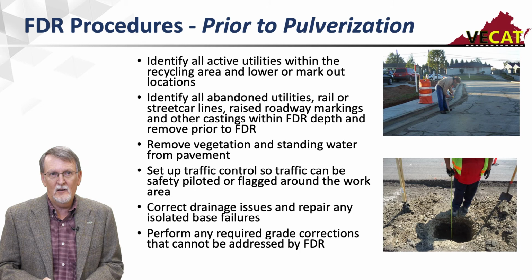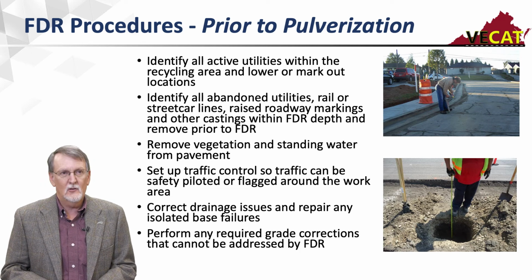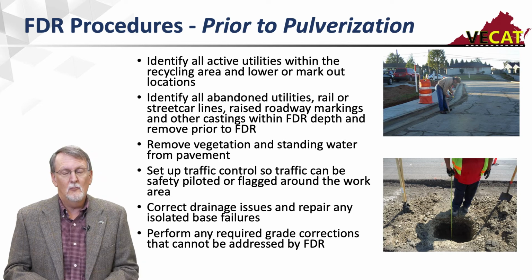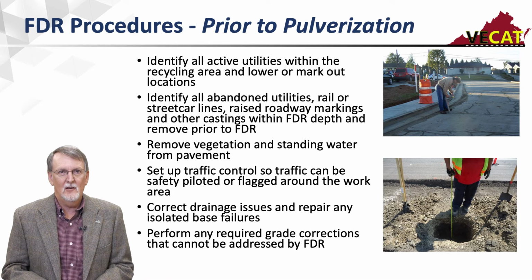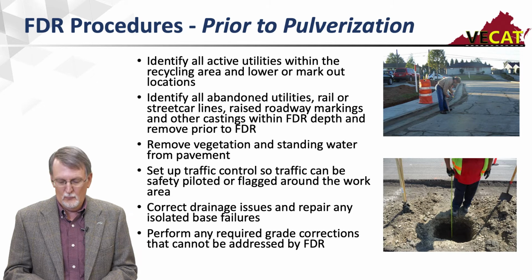If I have any drainage issues or any isolated base failures, it's nice to correct these before I get started. And any required grade corrections that cannot be addressed simply by the FDR, we want to get that done ahead of time as well, so I can get a nice uniform stabilized layer.